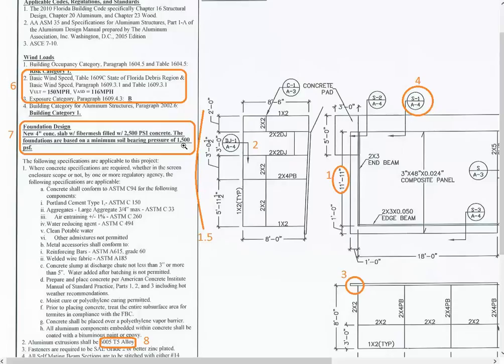And we can also work with what you have. If you have a certain type of concrete slab that was poured at this, we can get these things engineered to where they will still anchor in there. In some situations, if you've got something that's fairly minimally poured, maybe only 2,000 psi concrete, what we would do is space the anchors closer together along the bottom. So if you go up to a real high psi concrete, you could get away with 1 anchor every 3 feet, whereas with this, you're going to be at 1 anchor probably every 18 inches or so.